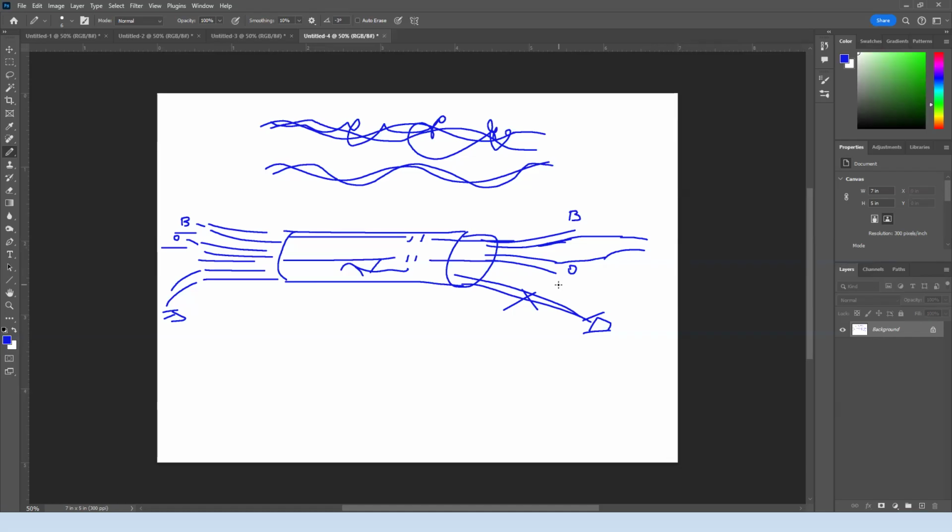And then you could let the office know, or whatever the company, that this is what you've done, and maybe we need to have some crews go there and pull some more wires because we have no more free pairs. So that's called splitting pairs. And that would definitely cause crosstalk between other pairs.